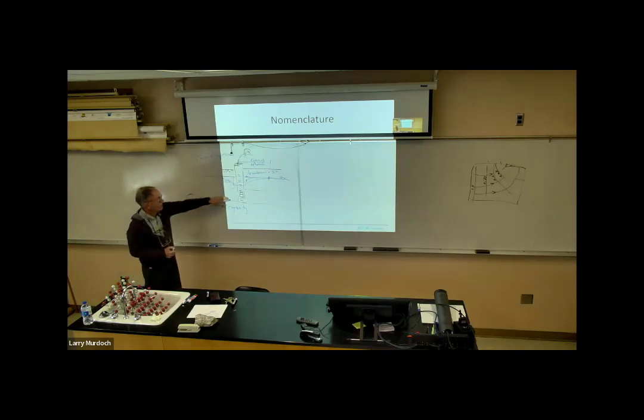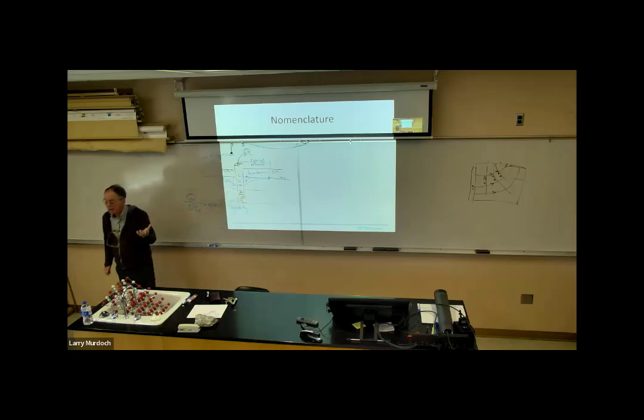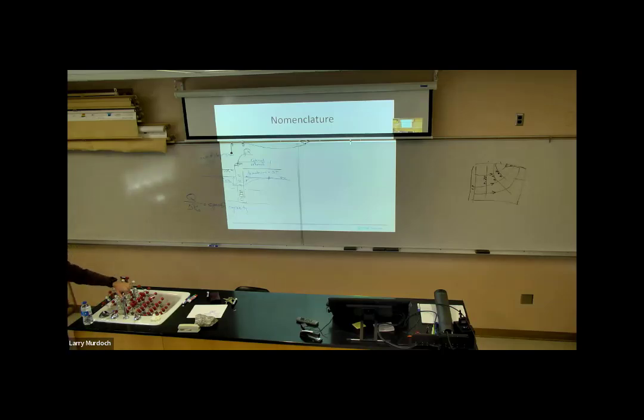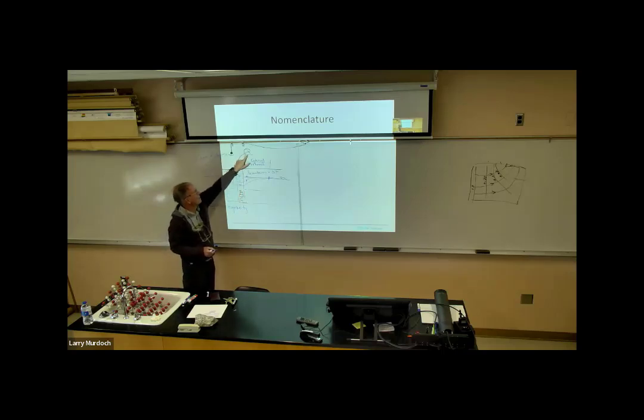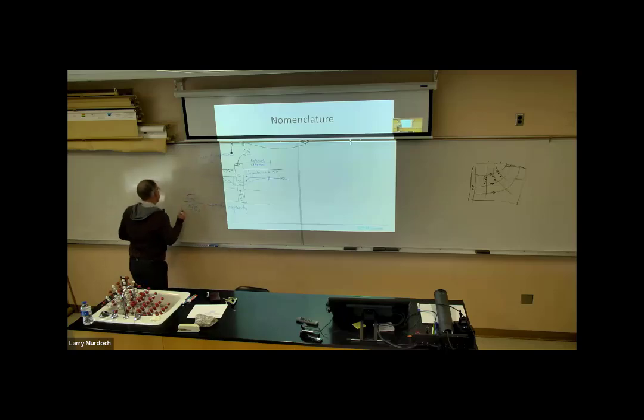Okay. So generally this is an electric motor, and we have to give it some power, and we want to be able to calculate how much power we have to give it. So this pump has to move water at this flow rate, and it has to lift it from here up to the ground surface. The higher it has to lift, that requires more power. The bigger the rate is going to increase the power.